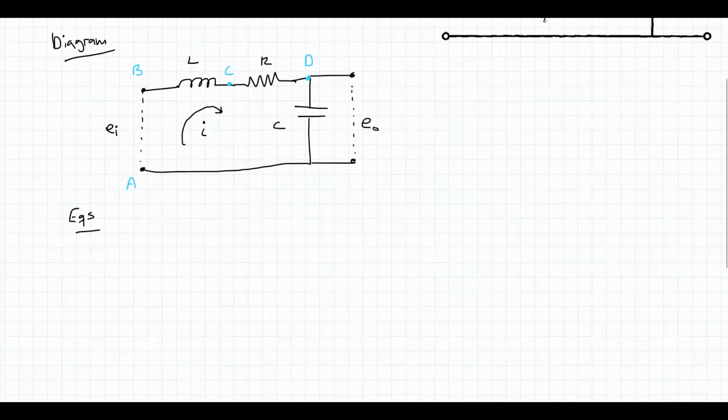Now, like I said, I'm going to start with a KVL. So I'm going to sum my voltage as I go from A back on itself, and KVL says that that net voltage has to be 0. Right, so as long as I go in a closed loop, I can make this equation. For simplicity, I am going to go with the direction of current as I've established it. So clockwise is the direction I will travel.